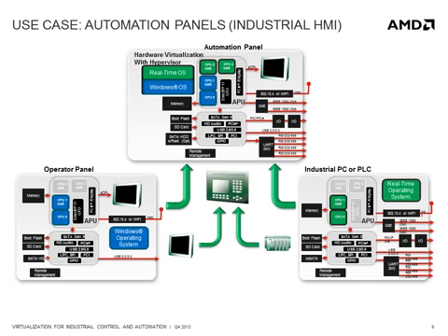To effectively integrate these two solutions, the integrated system must perform the functions of each just as well, if not better, than the individual platform. The key to achieving this is to leverage virtualization technology to enable processors to run multiple independent and isolated operating systems on a single platform. This allows Windows to be utilized to develop a fully featured and immersive graphical user interface and a real-time operating system implemented to perform time and safety critical functions. The latest technology processors offer virtualization support in hardware to deliver efficiency and excellent performance for the developing software architecture.